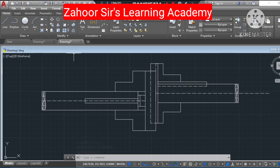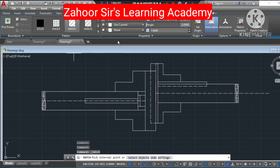Now the last thing left is to hatch it up. So we'll hatch it up. Before hatching we need to give these two things clearly. So for the hatch to be visible, I can increase the scale of that hatch. So I will keep it 5 so that it can be visible, and also the angle can be given there.